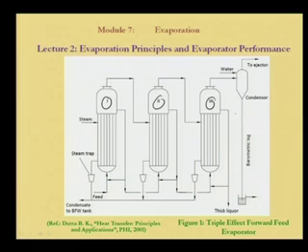The advantage here is that the steam we put in only once is used in multiple evaporators. The vapor which is coming out, its energy is used again for this evaporation. Therefore, the economy gets increased.